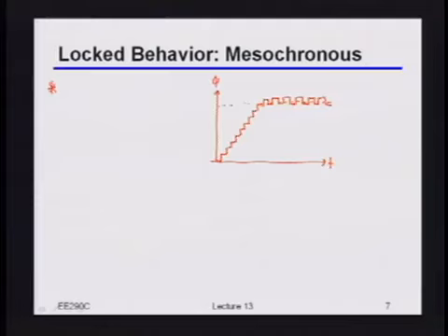Yeah, there we go. Okay, so the first thing you care about is just the worst case step size, right? Because basically, if I have some DAC kind of looking thing, which is that phase interpolator, which is just translating digital codes into phases, and I know that I'm always going to be jumping back and forth, then what I care about is the biggest jump that I could possibly be taking. Because that sets the magnitude of the dither that I'm going to be getting in my system. Right? It's absolutely true.